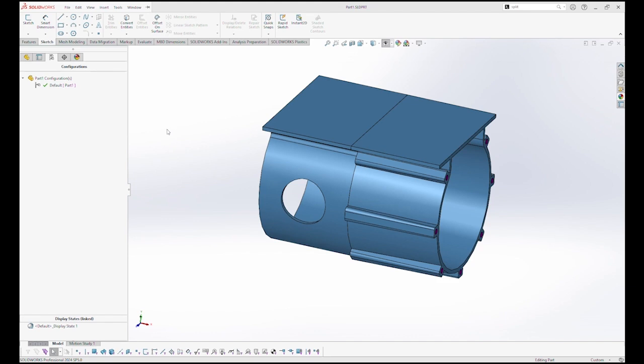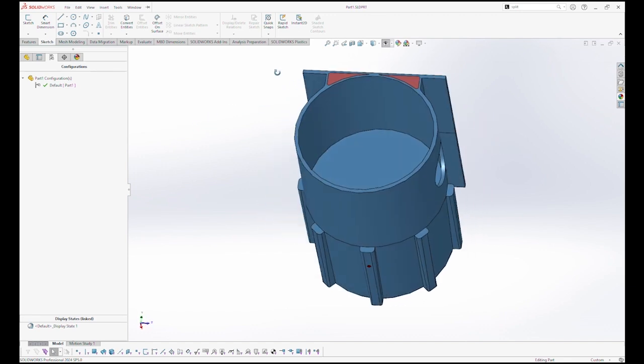Today we're going to talk about wall thickness. We're going to talk about parting lines, draft. We're going to talk a little bit about subgates, ejector pins, slides, and last but not least, talk a little bit about surface finish. And we're going to do so on this part that I'm showing you on the screen.